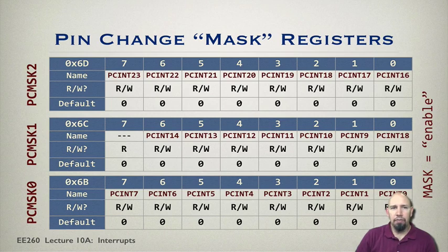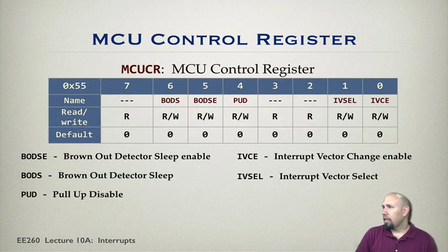If we set that pin's bit to 1, we enable that interrupt, or that's part of the enabling process for that interrupt. There's actually multiple layers of interrupting for pin change interrupts. They're a little more complicated, but it's not too bad.